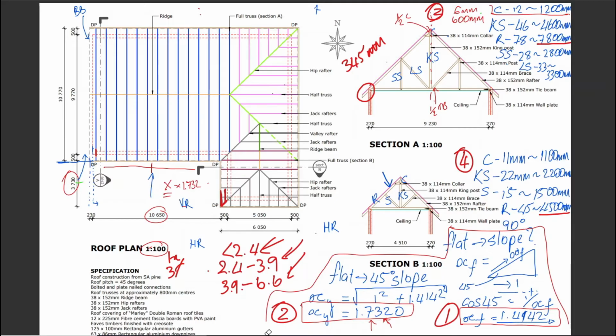In the absence of any evidence, you make the assumption, right? Because it's a tiled roof. We'll take the span. I stand corrected. That could be different. And in your spec, you don't actually have a description for your tilting fillets. What I said was it is a 38 by 50, same as the previous example we've worked through. And tilting fillet on the outside, with the 50 mils upwards to allow that tile to be pushed up a bit more. And then your batten on the inside in yellow.